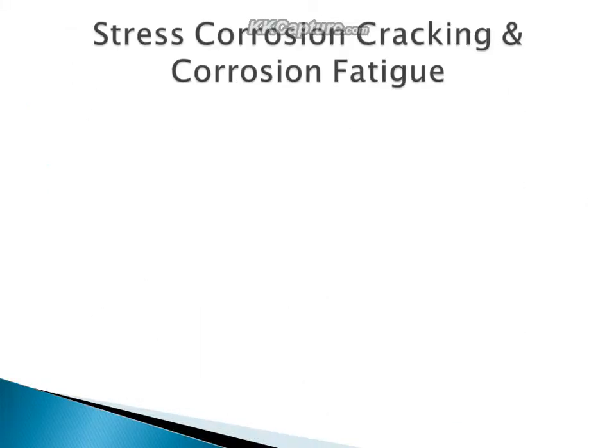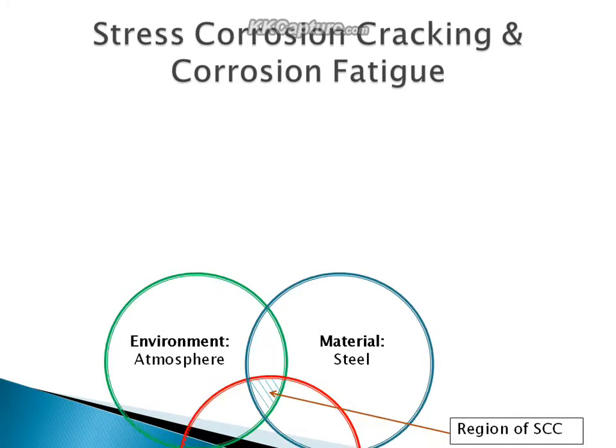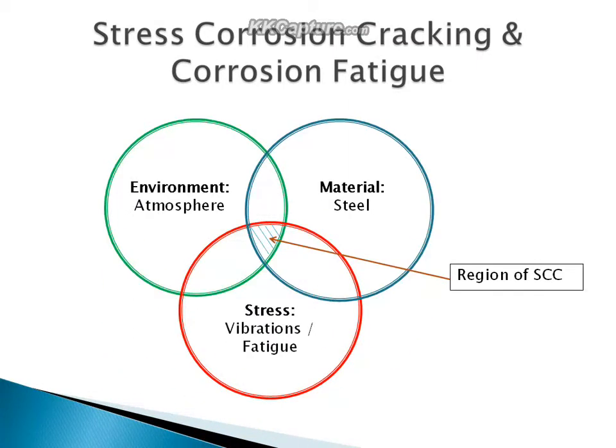Stress corrosion cracking is another form of corrosion in which a threefold combination of material, environment, and mechanical stresses creates a situation where the material corrodes under stress. This often results in failure well below the yield strength of the material. Failure can occur suddenly and unexpectedly.